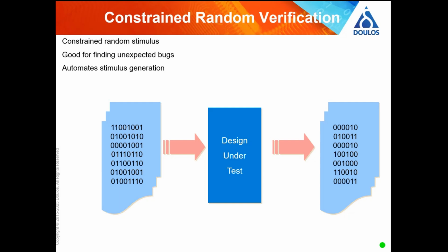Okay, let's write something to an address and read it back. That's a pretty dumb test because a capacitor will pass that test. Your bus might just remember what you wrote. Okay, better test. Let's fill up the memory full of things. Let's write 0 to 0, 1 to 1, 2 to 2, 3 to 3, and then we'll read it all back. Okay, better test.